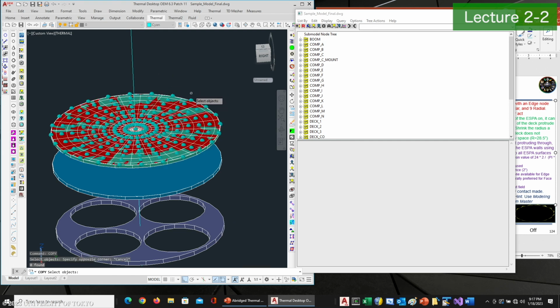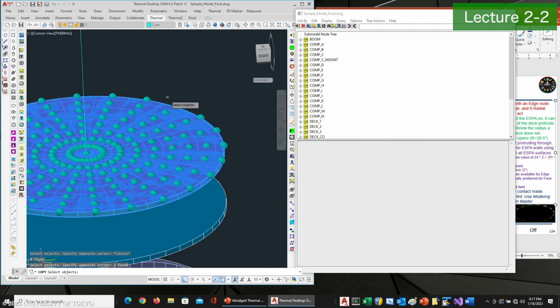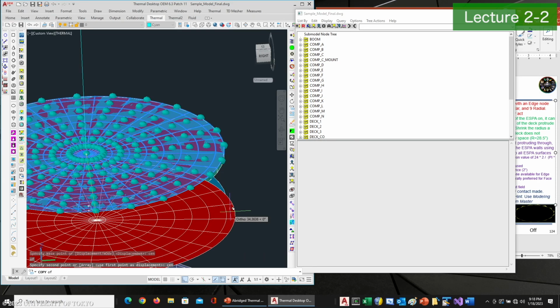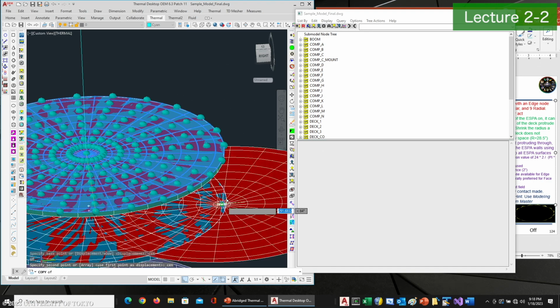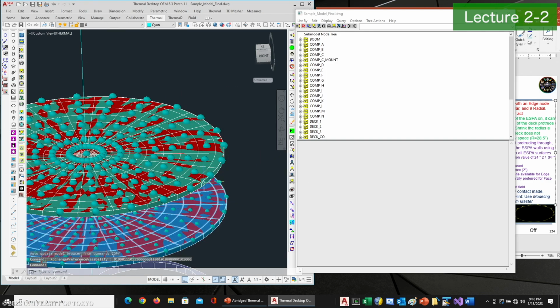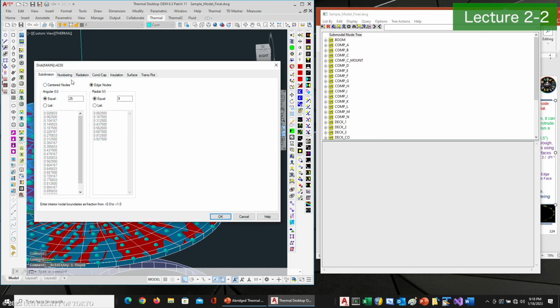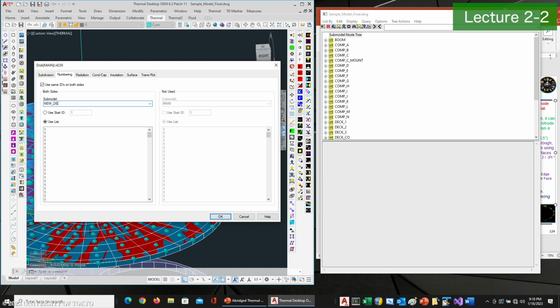So I could do a selection here for crossing and then remove by typing R to remove from the selection set the solid. So now I've selected 2 objects, removed one from it, and now all I have selected is the disk. So I can copy that from the center here to the center down here. So there I made a copy of it. So I'd call this one, and in this case it does let me select it sometimes easily, sometimes it doesn't. So there I would edit it. We'll call this new deck 1.